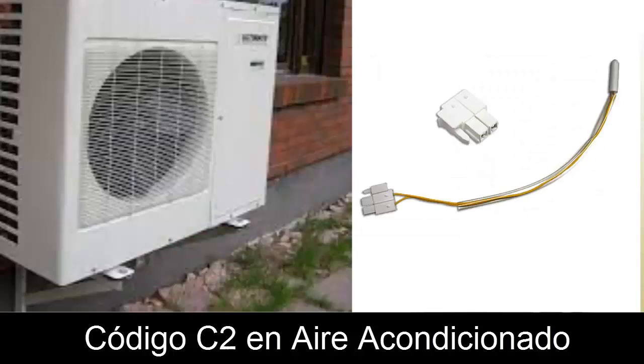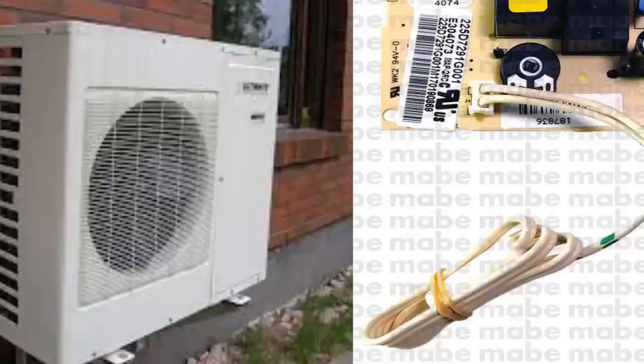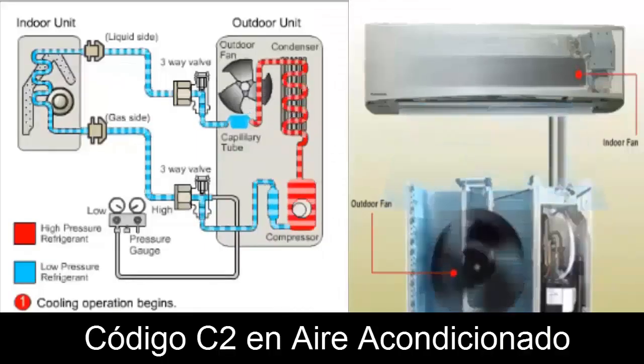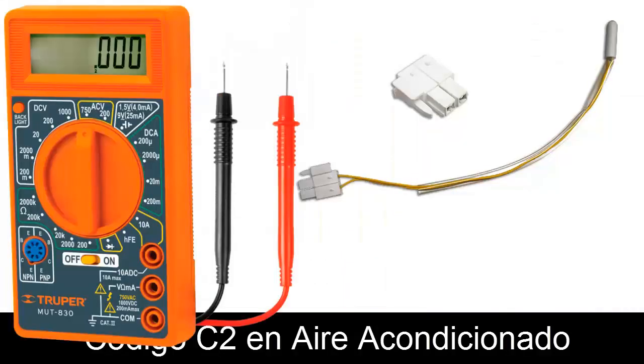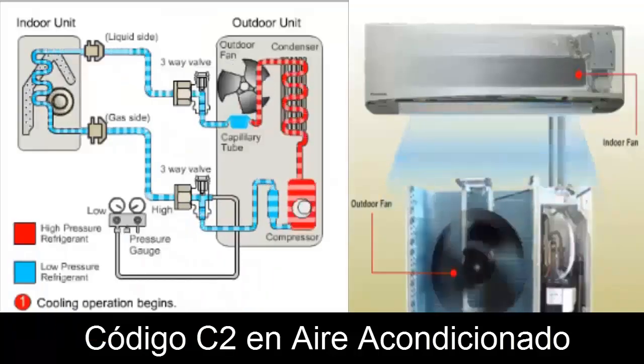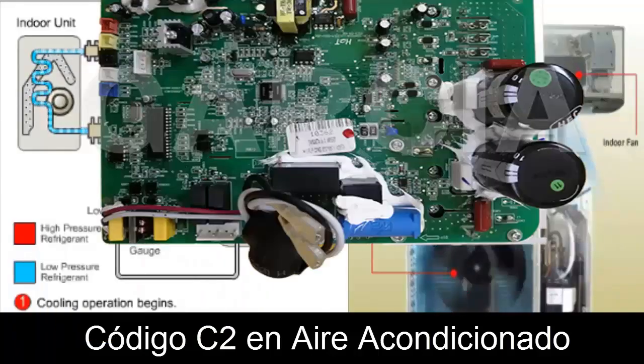A. The thermistor sensor is shorted or open. B. The thermistor is not connected to the interior PCB printed circuit board. C. The thermistor's resistance is incorrect. D. Damage or defect in the detection circuit of the interior PCB.